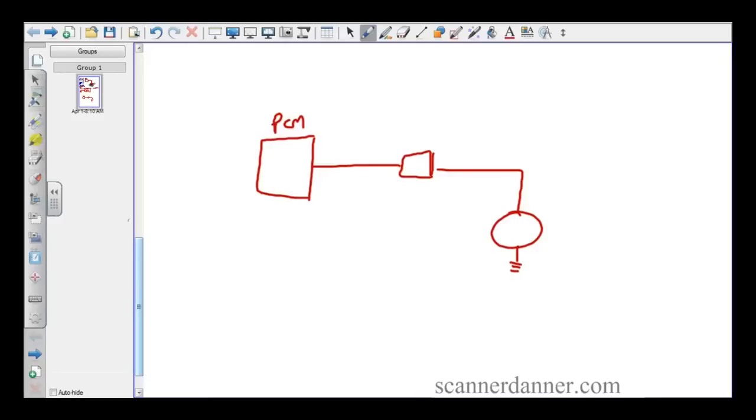There are certain inputs that this computer is going to need to turn the AC clutch on. So we would call this side an output, and this side our inputs. You guys that had air conditioning, what are some inputs involved in whether or not to turn that AC compressor clutch on? Temperature would be one. If our ambient temperature is too low, there are varying sensors for that. We'll just keep it generic. So I like that. We'll call it our ambient temp in some way, shape, or form.